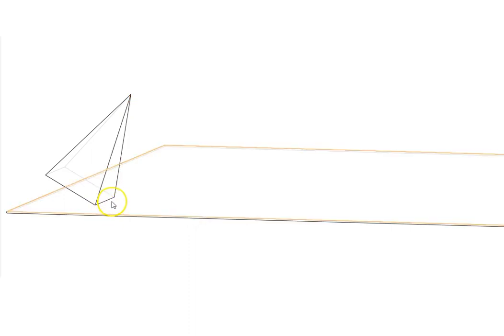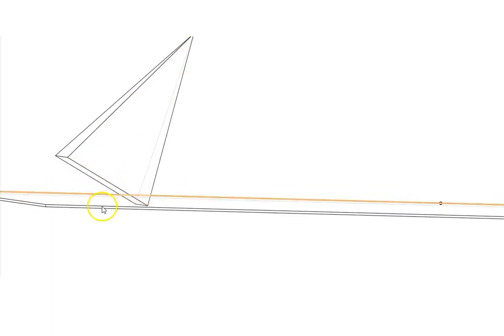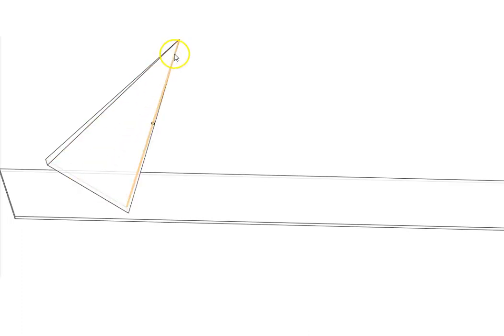To put it in a different way, this question could be asked in multiple ways. For example, a square pyramid with height 100 mm and base 80 mm is tilted with respect to its base at an angle of 30 degrees to the horizontal plane. This is one way it could be said. Another way it could be said is that for the same square pyramid, the axis of the pyramid is tilted at an angle of 60 degrees with respect to the horizontal plane.